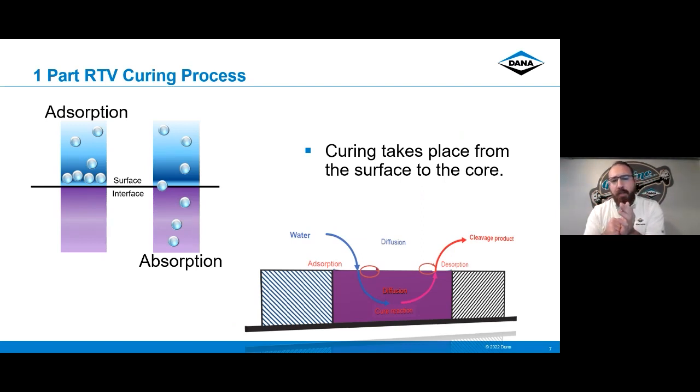Now, when you're talking about the diffusion that happens in the center, that doesn't happen immediately. That takes time. And that's why you have cure windows. Some people like to put a bead of silicone down, slap it together, and send it. It's good to go. Ideally, you're going to want to let that silicone sit and cure before you put it under any type of immense pressure or any type of stresses, shear stresses, tear stresses, heat, temperature stresses, right? It needs time so that it can cure.